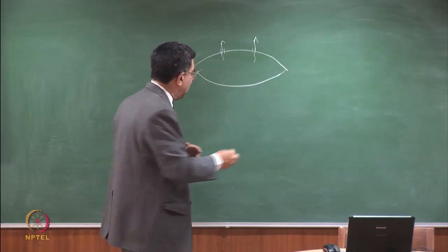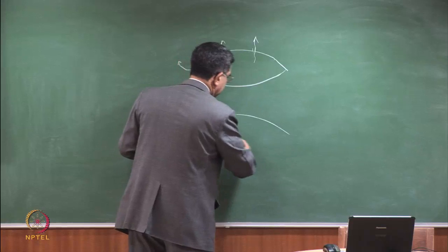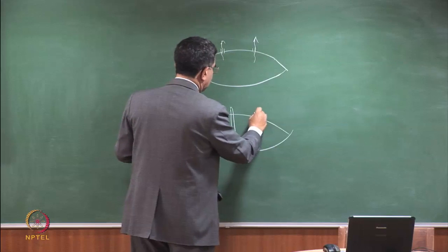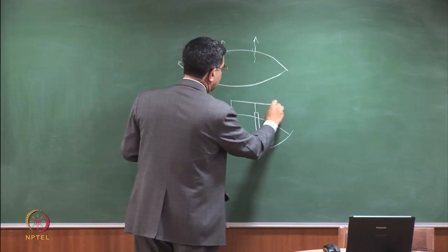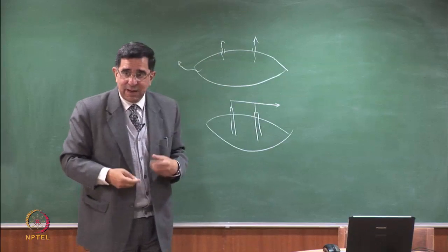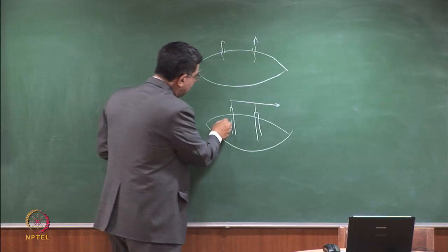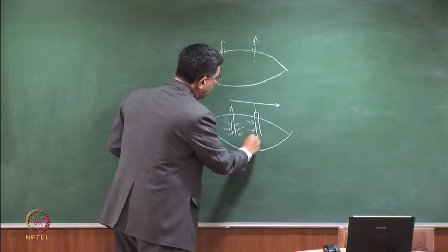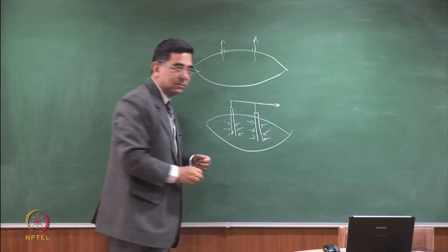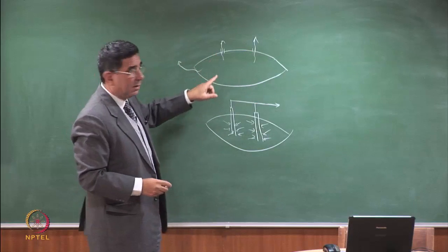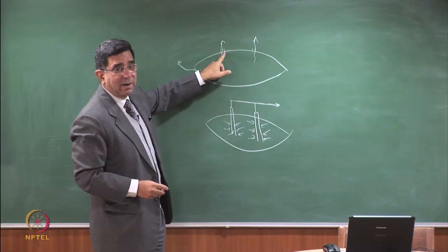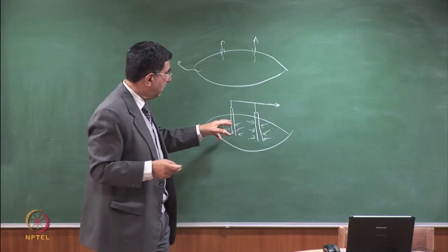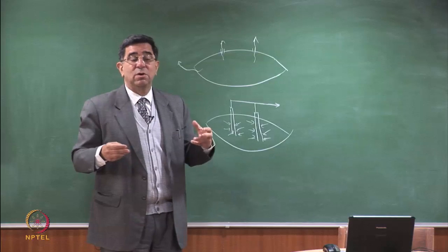Okay? Instead of this, if I have the same system, but now I use an active system, and I'm sucking out the gas or the air, what is happening? Whatever is inside this is going to this well. So here, gas used to travel and come out. Here, the gradient for the gas to travel is more. Why? Because you have a negative pressure inside this. So you collect more gas.